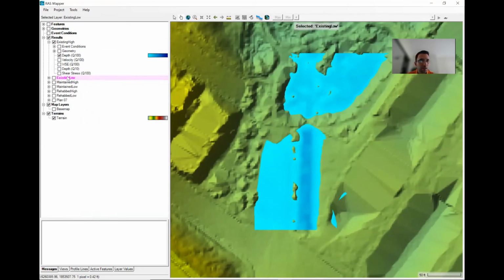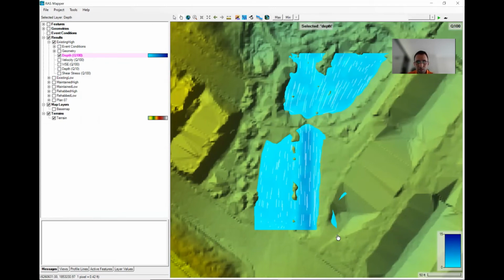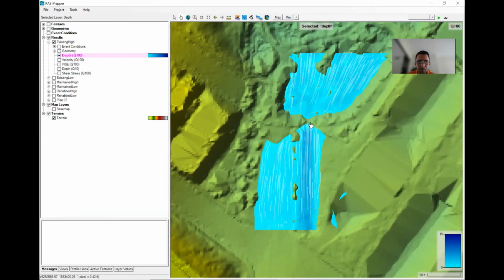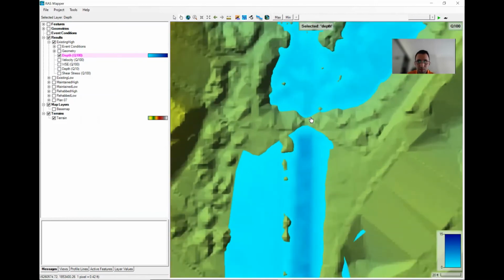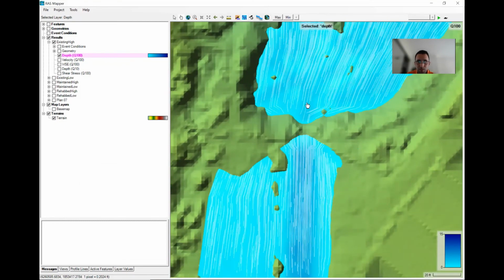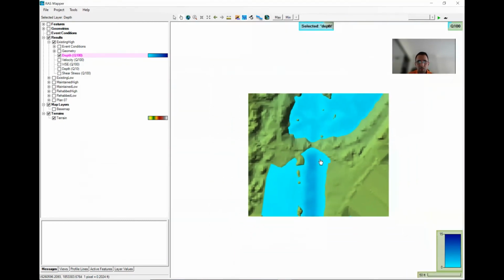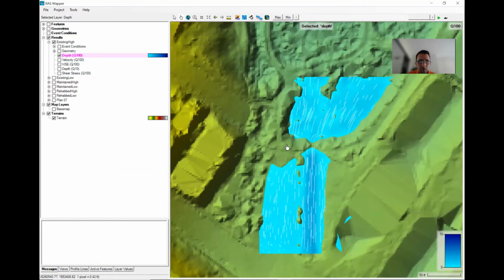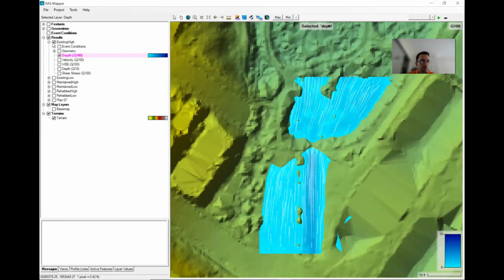I can select this and then do particle tracing. So you can see how water is moving. It's now going to this culvert. And then from the culvert, you can see how fast they're releasing. So it's because it's supercritical and now coming back to subcritical. You can show velocities. We can change this, maybe